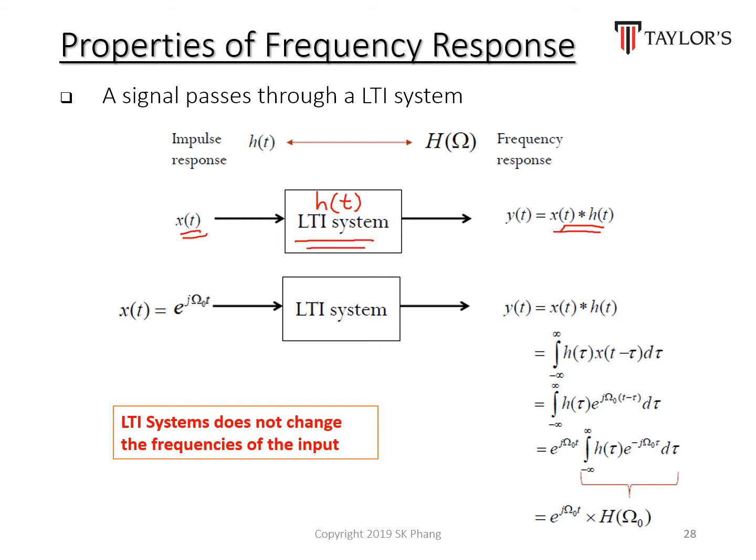So in frequency domains, when you have already convert the signals and the systems into frequency impulses, and according to the derivations over here, which you can go through it slowly, it says that in frequency domains, the outputs of the signals, let's say y omega, is equals to the input of the signal multiplied by the impulse response of the systems.